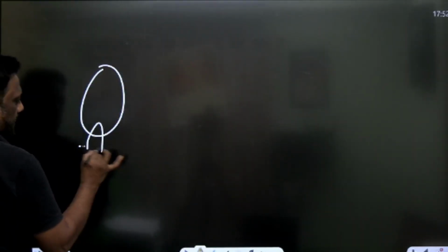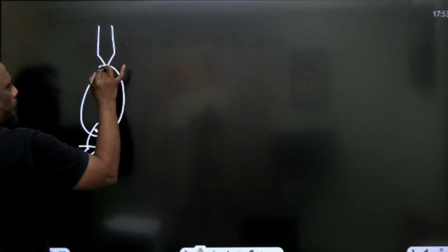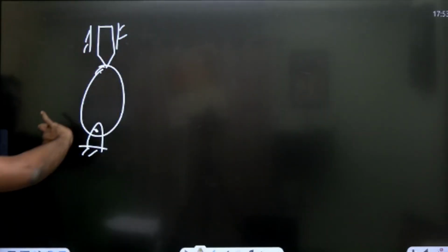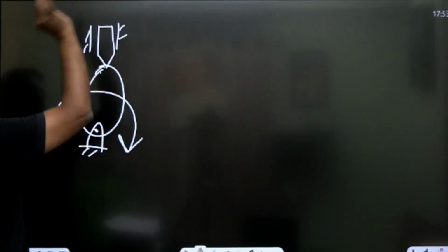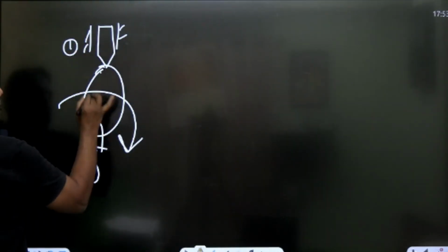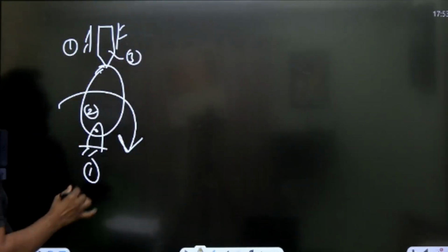Look, for example, we have a cam like this. Now, let this be the follower. Let me give input to this and you have output. So how many links are there, sir? Fixed is 1, cam is 2, follower is 3. Very good. So, let me write.